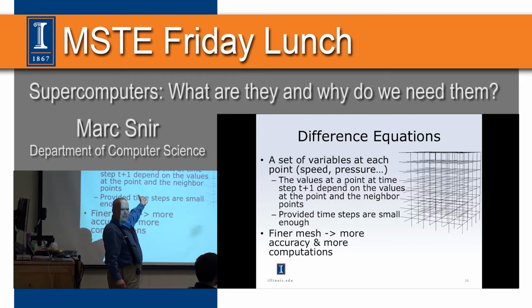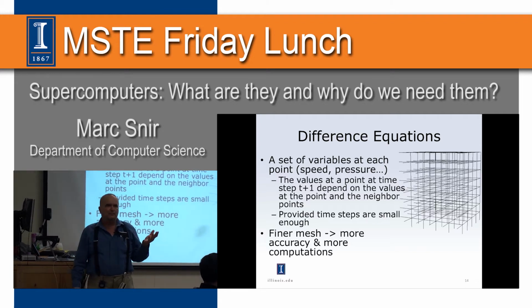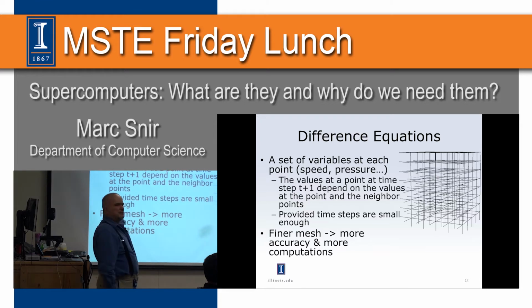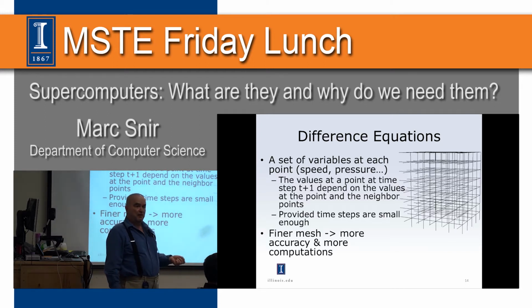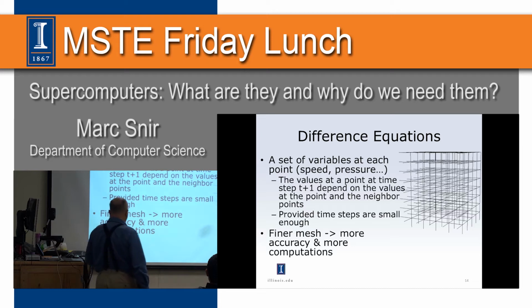Typically, if you simulate atmosphere, you care about the speed of sound, which is as fast as things propagate in the atmosphere. If you look at simulating biomolecules, you care about the speed of light because you simulate fields, electrical or electromagnetic fields, which propagate at the speed of light. So the molecular simulations that I've shown you are using time steps which are measured in femtoseconds to be able to get this locality property right. The climate simulations that I've shown you use time steps which are measured in half an hour or things of that ilk.